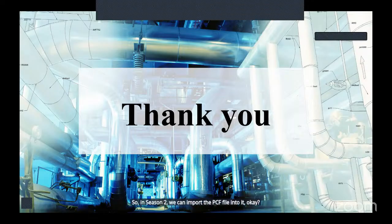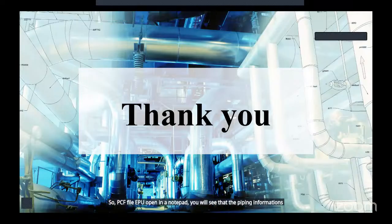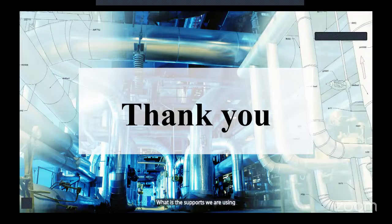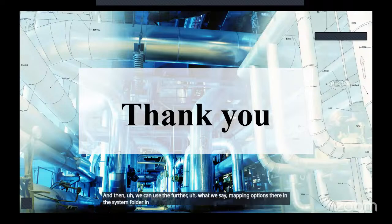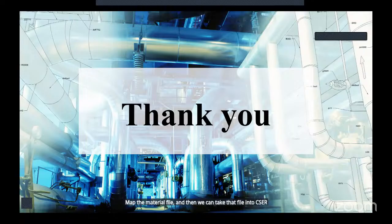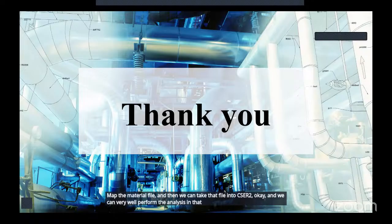If you open a PCF file in a notepad, you will see the piping information: the line size, the thickness of the piping, the material, and the supports we are using. That PCF file can be taken as input in Caesar 2, and then we can use the mapping options in the system folder to map the unit file, the SIFs, the support file, and the material file. Then we can take that file into Caesar 2 and perform the analysis. Yes, through PCF it can be done, no other format.